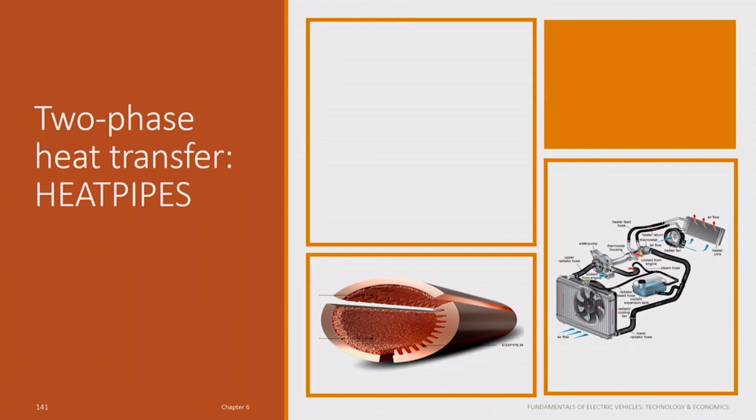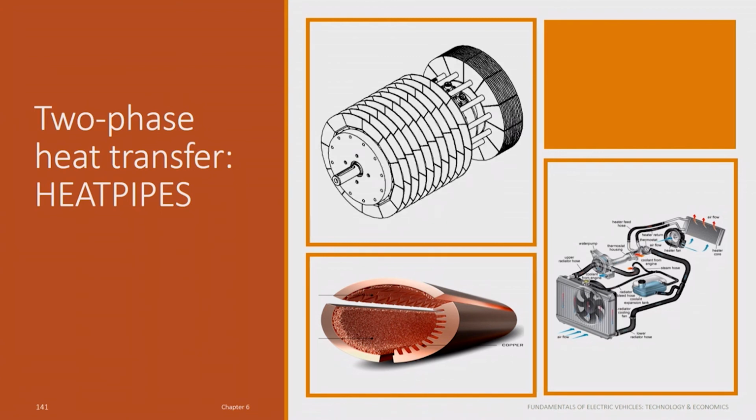So, something called a heat pipe is a hollow copper pipe, but it can conduct 100 times better than a solid copper rod if I have a few drops of water inside it. That is the construction of a heat pipe. This is just a cross section showing different constructions, and we have used that in designing a higher power, higher wattage motor, where some heat is removed by air in the normal way, but much of the heat which is beyond the capability of air to remove from here is conducted away by heat pipes.